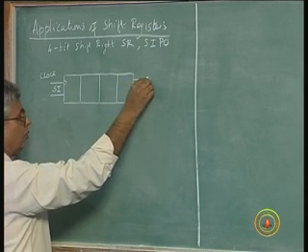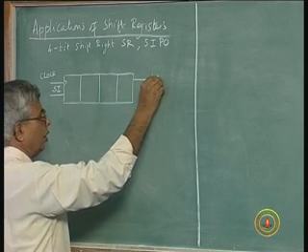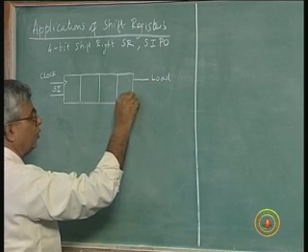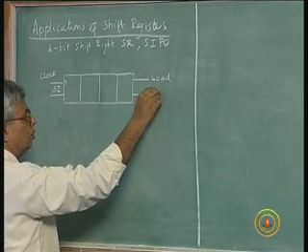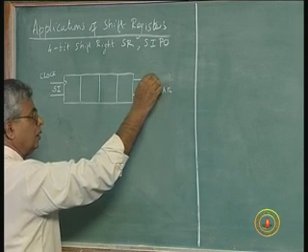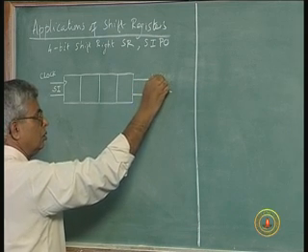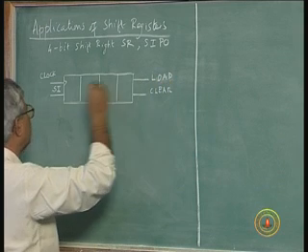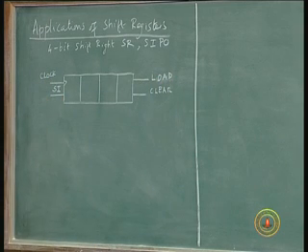We should also have load and clear features, because you want to start with a pattern. You can do that by putting the data in one bit at a time and shifting it. That is one way of loading. The other way of loading is to give parallel inputs and then give all the bits at the same time.